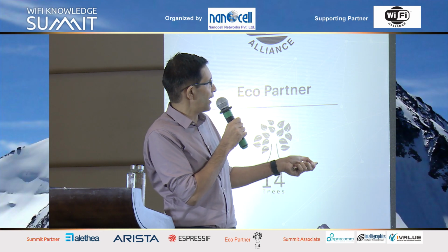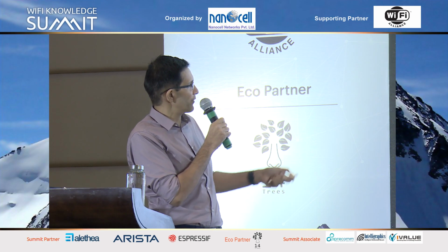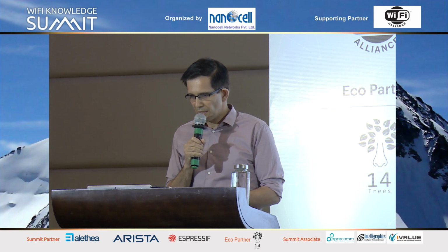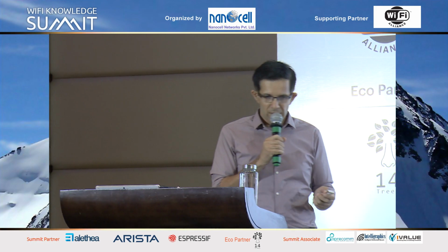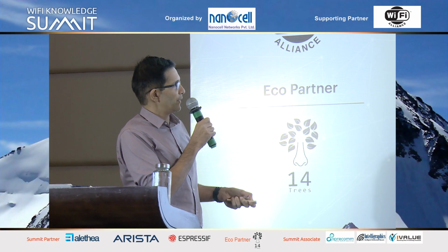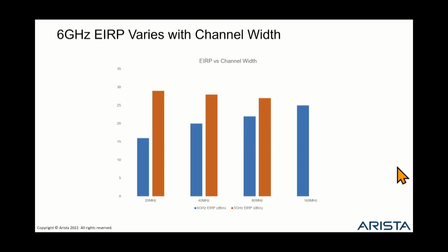But again, even for glass, there's a significant difference. So these are, again, path loss with obstacles. And last but not least, this is an interesting aspect of 6 gigahertz behavior that we've all talked about, the 5 dBm per megahertz.